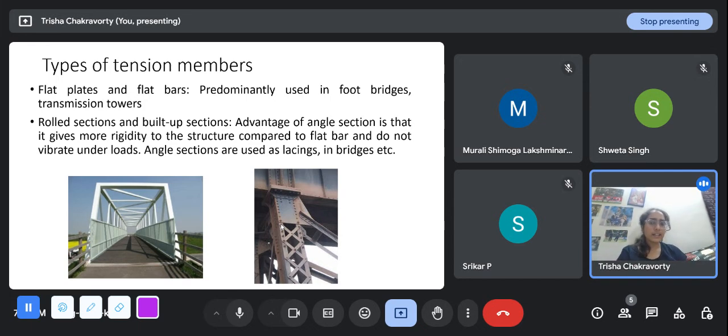In that we will see that buckling is a very important issue there, not in tension. When a member is under tension it cannot buckle, but when a slender member is under compression it can buckle, right? If you can perceive what buckling is: suppose there is a column, and you put a compression force, and it does this bending.